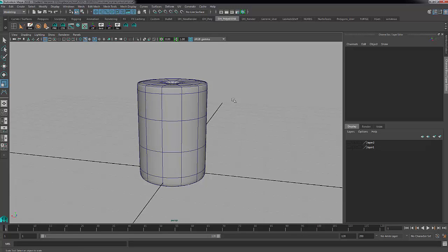One of the reasons that I say that I'm going to deal with these later is because when you're dealing with Booleans, a lot of people have problems with Booleans. They say to me, well, the Boolean tool is very unreliable. It doesn't work right all the time, and it's just a little wonky. And I think that the real truth behind that is that it likes to have very, very simple geometry. So I try to use primitives or just initial shapes like revolves and things like that. I try to break it down into its simplest parts, and then make sure that your construction history is off as well.